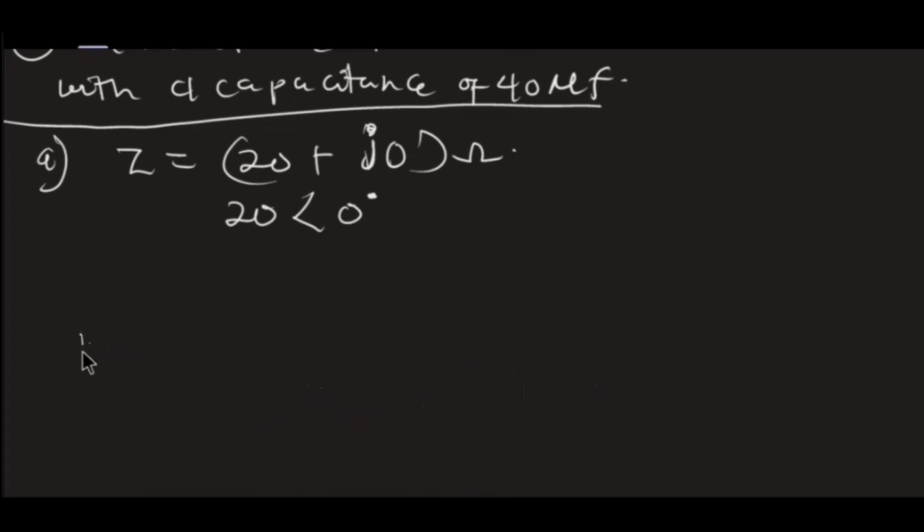So now the second part is saying that you have a resistor R equals 20 ohm, then you have our XL, the inductive reactance, but they were given inductance L. So I have my L equal to 0.1 henries. Now, whenever I have L, I need XL.